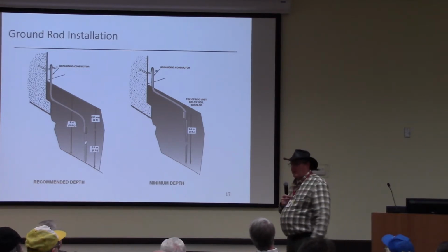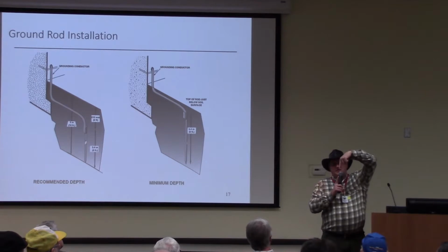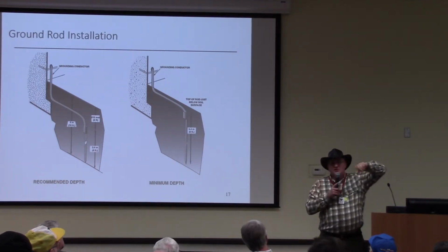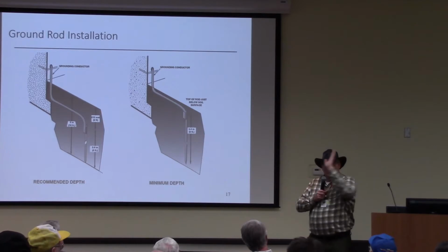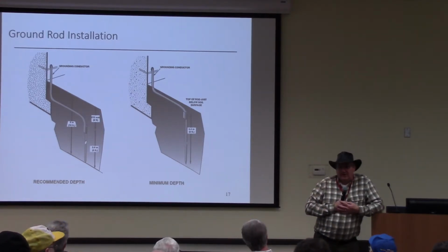All right, an arc gap protection is basically a device that has two very sharp points set at a specific distance between them, with a gas inside that area, such that it will break down at a certain voltage and shunt or direct the current away from everything downstream from that. Okay, yeah. That's how that works.